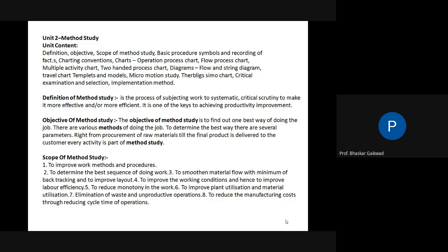Suppose you are manufacturing conveyor parts. What is the present method? First, you go for blanking, piercing, then the manufacturing of the pin, bush and roller separately, and then we go for assembly. Before assembly, heat treatment should be there. This is the ongoing process in industry. Now you have to study this process and see how we can reduce the cost of manufacturing.